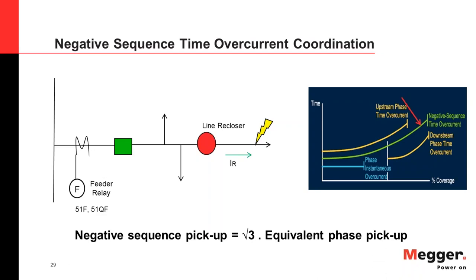For example, you said a loss of potential relay picks up on a decrease in positive sequence voltage only, and some other relays monitor only negative sequence current. When testing with the software, you enter the sequence values you want, and it calculates what the input should be. So the relay doesn't actually see the sequence values, but the unbalanced and out of phase inputs. That's absolutely true.